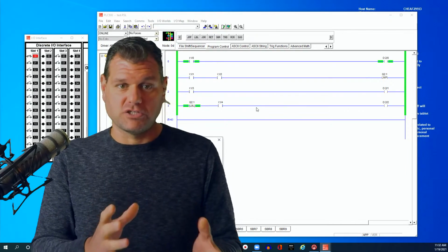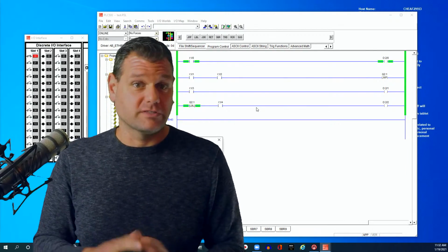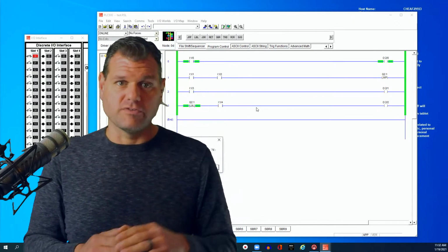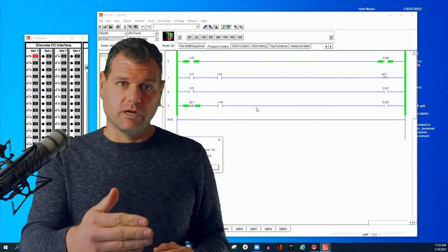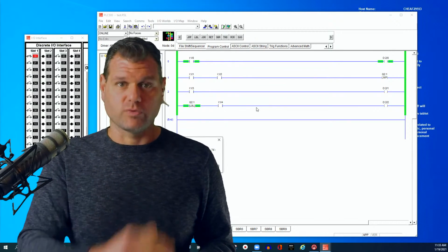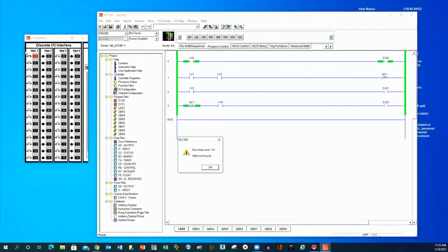So if the condition is now changed where it doesn't skip over that, you can have it run and scan over it. It's not necessary, but you could do that because it'll catch on the next rung. If whatever rung told it to jump is now false, it's going to scan everything the next time. So it'll scan 20, 21, 22, 23 all the way down. All right, so that is the jump. And again, you can jump back and forth. You can jump anywhere you want.